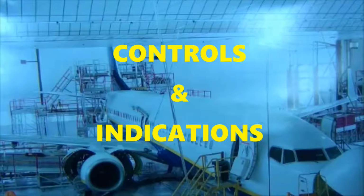You also have the attitude data that's received through the air link, and that's during flight. That's all coming from the ADIRS, and that's going to be used as an alternate source of the attitude data. Okay, and then again, also the control of automatic aircraft fueling. So that's part of the quantity indicating system, providing all these different functions.